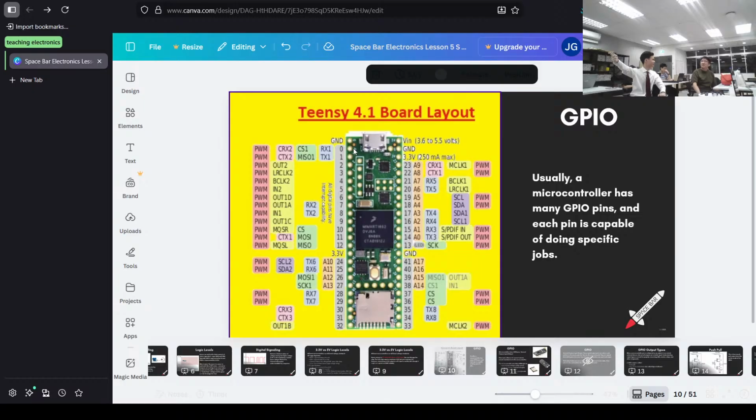See how dedicated pins have certain functions? Not a problem for ESP32. That's one of the reasons why we like it so much. When you're designing boards where you can't remap the pins, you have to take note of this, especially the capabilities of each pin. Usually there are nice graphics that allow you to see at one glance which pin supports what.